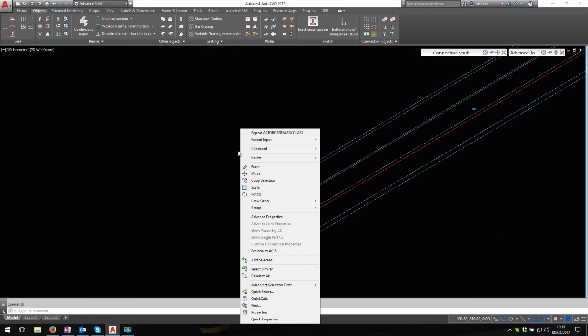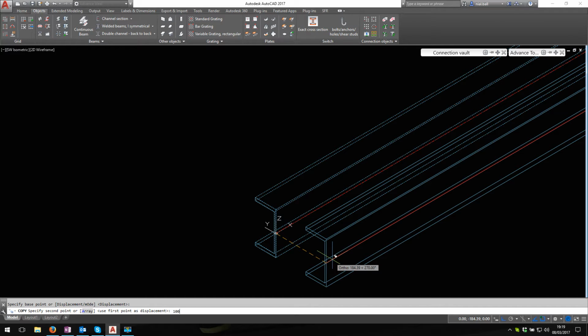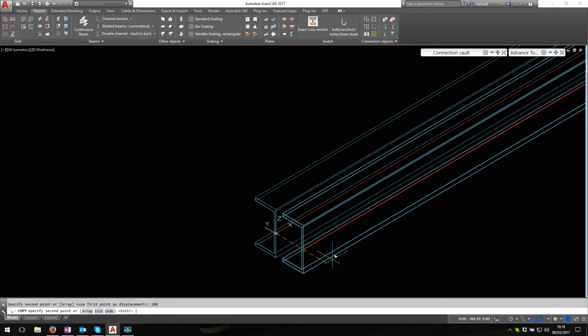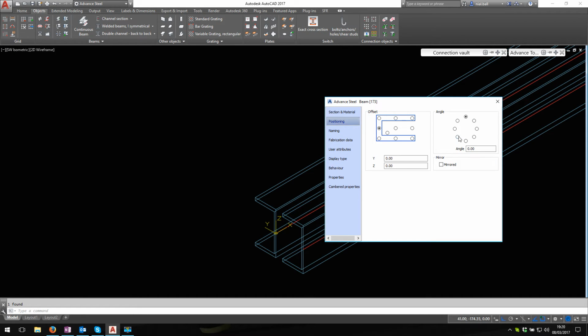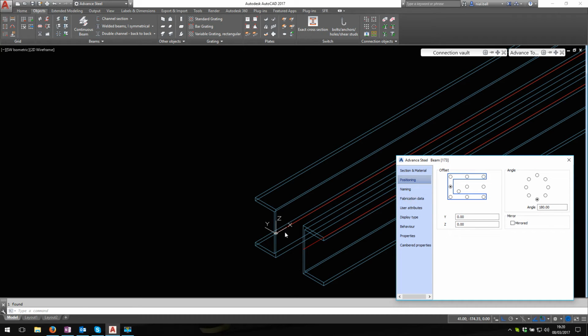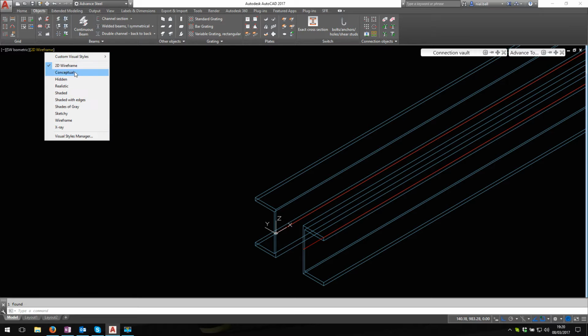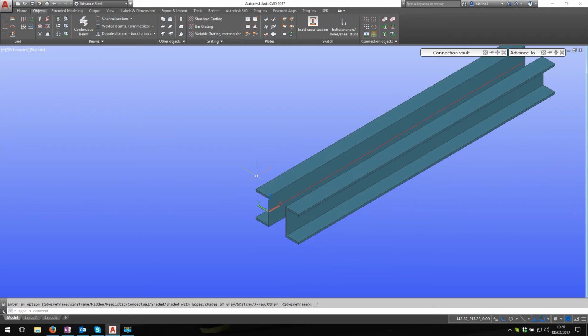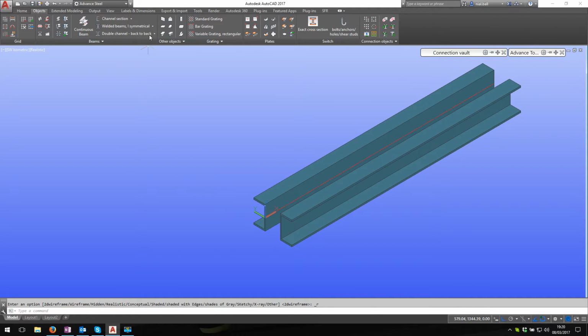And what I'm going to do, I'm going to copy this. So I'm going to copy it from here out 100 mil. Now remembering that the system line retains its position when I reposition the beam, I'm going to flip the beam there. Look, I know this is 100 mil spacing. Let me just put this into realistic view, see what's going on. There it is, look. So 2 beams back to back, you'll recognise this, as I said, if you do headers.